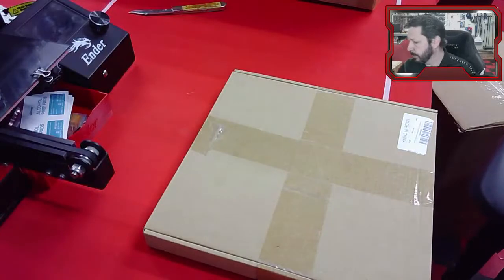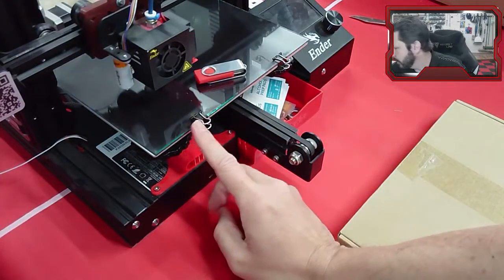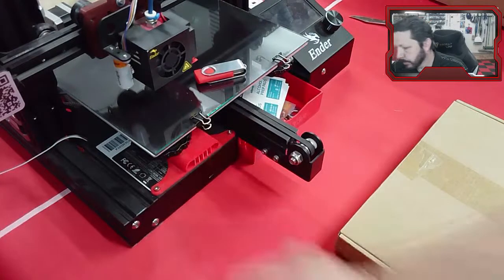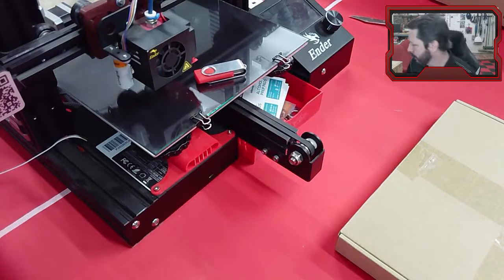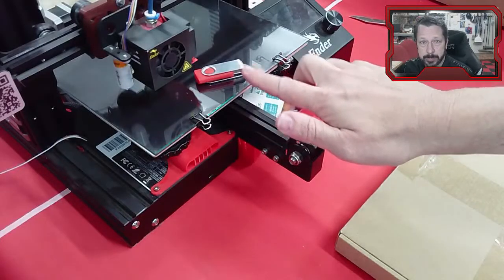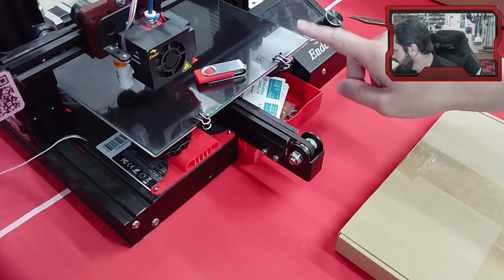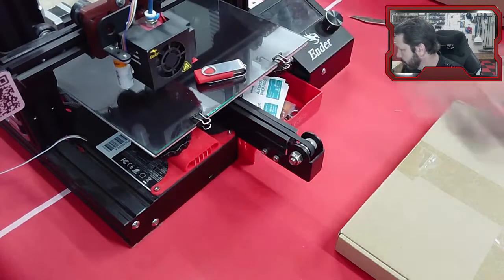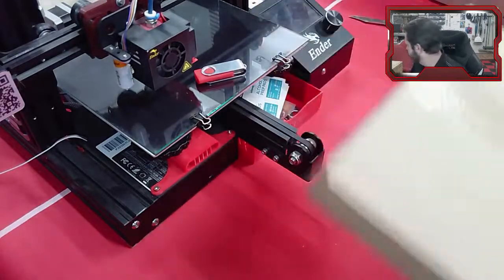This is going to be a bed. So one of the things that you could do is, right now I've got a sheet of glass on here. It does not come with that, so it comes with just a regular plastic type material, fiberglass reinforced plastic bed usually is what's in there. I've just added a cheap picture frame from probably Walmart or somewhere, and cut out the right size glass to put on here, and I'm printing directly on top of that. This one is probably a special version of that.